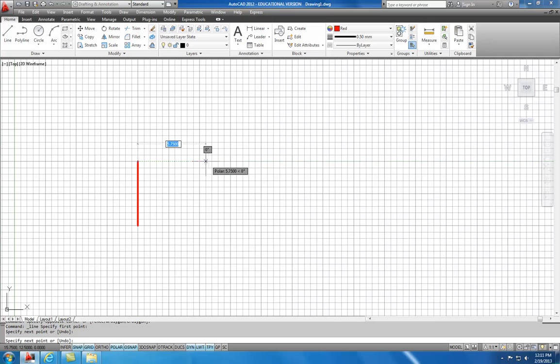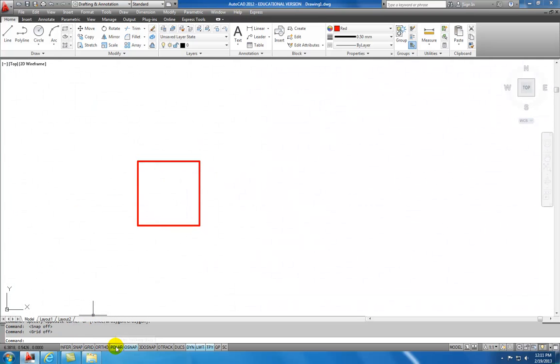And this is the old way of doing CAD, snap and grid, where I could set up a grid and a snap, and my cursor will highlight those values and stick within those parameters. The new way, and it's a much faster way, is not to use snap and grid, so I'll turn them off. It's to use polar.